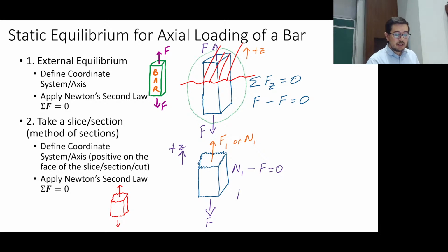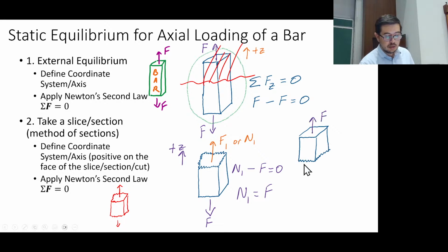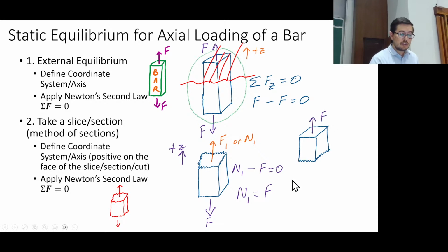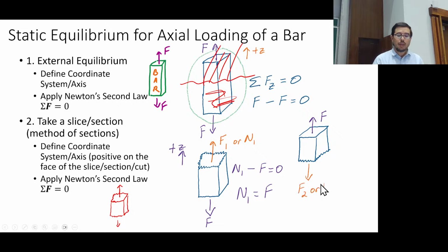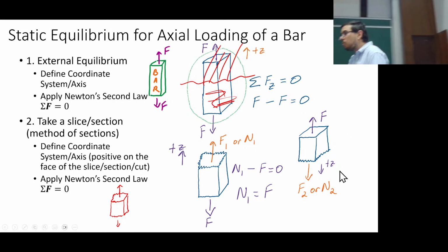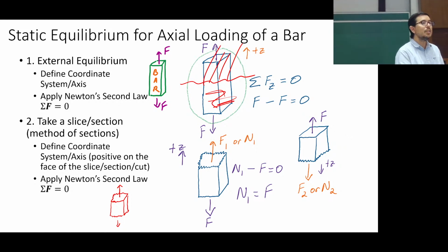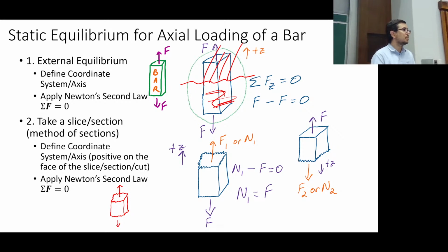What's interesting is that this surface, depending on how you do the cut, like this, you see now this is covering up the bottom portion. So now we've got the top exposed. You see here, we have now a surface with a force coming out, and I would suggest that you often define the normal vector coming out of that sliced surface as being positive. Okay, this is applicable to torques, it's applicable to bars and forces.